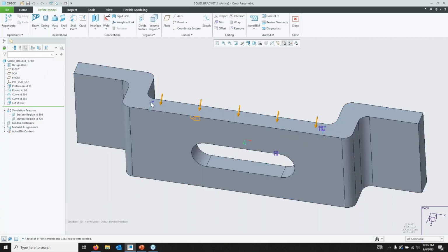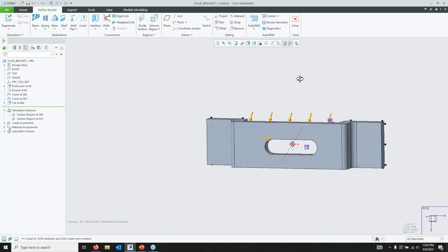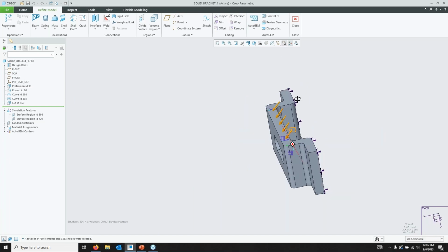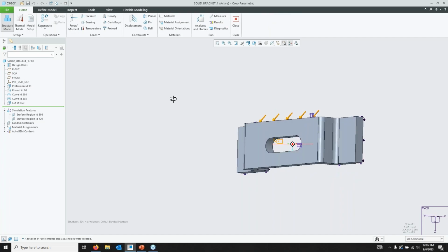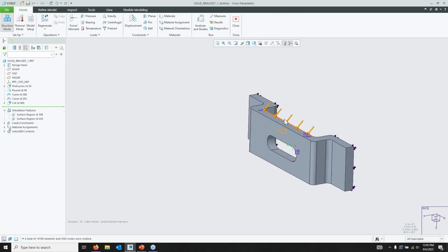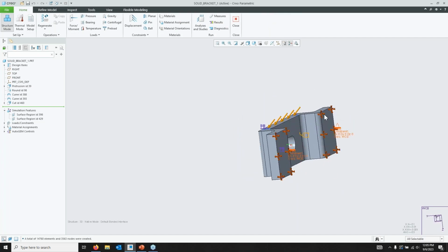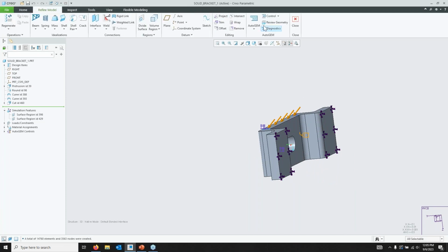Okay, so I generated my mesh, I added my material, and I did my loads and constraints. The final step is an optional step, idealizations. And I'm going to make it easy for us today. We are not going to be doing any idealizations in the introduction webinar. So for us, we really only have those 4 required pre-processing steps: the material, the load, the constraints, and the mesh.